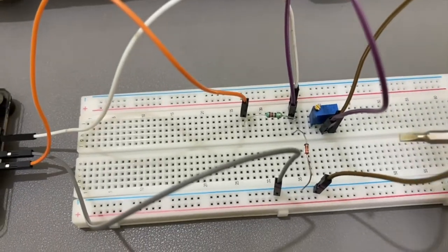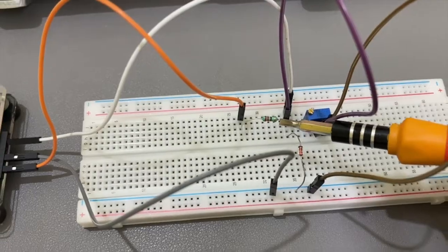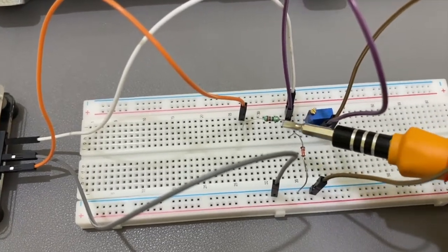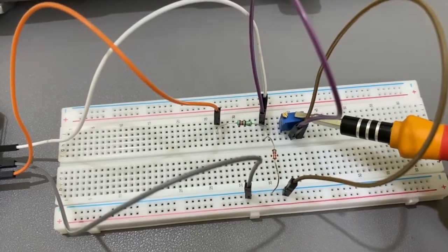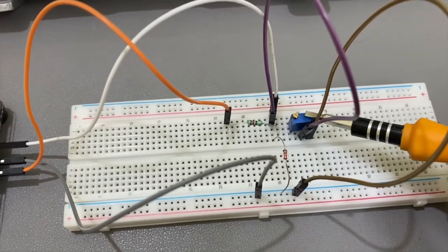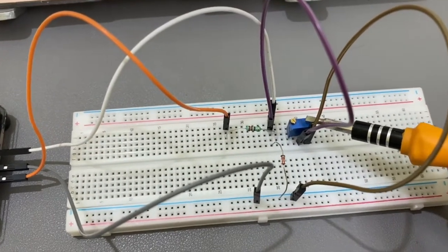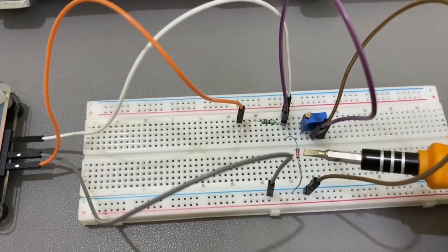The green resistor is Rs, which has a value of 220 ohm. I had to take a resistor of 250 ohm, but I don't have that, so I have taken a resistor of 220 ohm. This is a potentiometer, which is a load resistor. The value of this potentiometer is 1 kilo ohm. I had to take a 10 kilo ohm load resistor, but I don't have that, so I'm taking a load resistor of 1 kilo ohm. This is my Zener diode, which has a breakdown voltage of 3.6 volt.